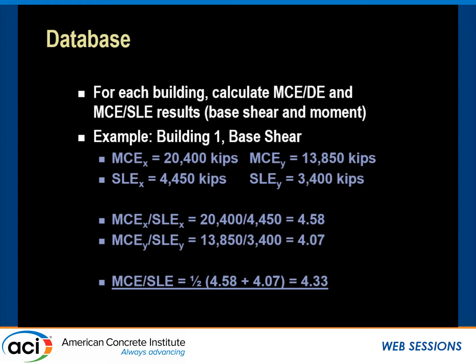So when I talk about MCE divided by SLE amplification factor, it's the average of the X and Y direction for the building in question. And that's the one value that we assign to each of the 14 buildings. We did that for base shear and moment for DE and SLE. So each building has 4 amplification factors.